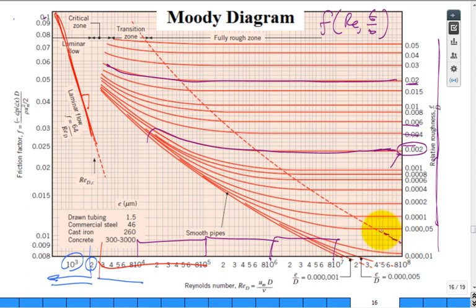Professor, what's this dashed line for? It separates two regions of this turbulent region. All right? So everything over on this side of it to the right is unique versus everything that's below it to the left. Well, they give this region out here a name. It's the fully turbulent, fully rough zone, etc. There's a couple ways of saying it. This book has fully rough.